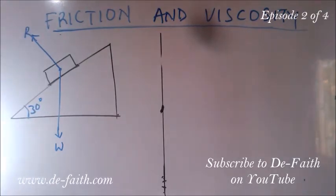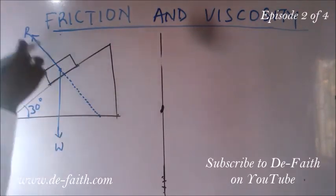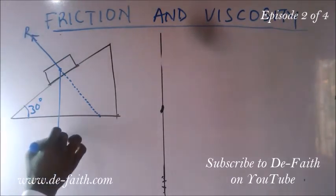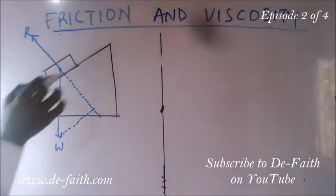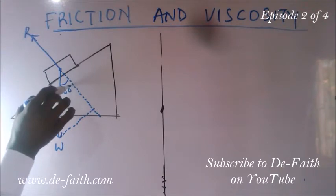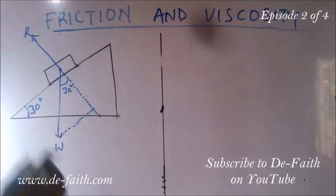Now first, we need to be able to resolve our forces. How do we resolve our forces? We need to realize that this is the actual opposite direction of the normal reaction, and so we can resolve it such that this goes in this direction, that is, this particular blue line is parallel to this black line. This 30 degree here is equivalent to this 30 degree here, because as this plane was raised by 30 degree, the angle here also will be 30 degree. And so for us to resolve these forces, we could resolve it as this.